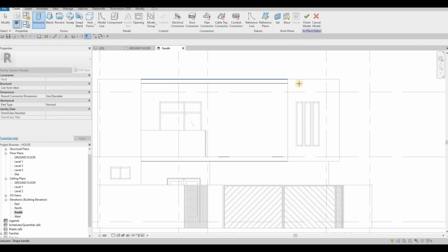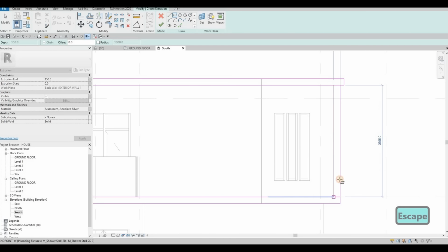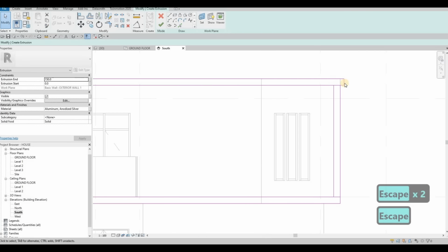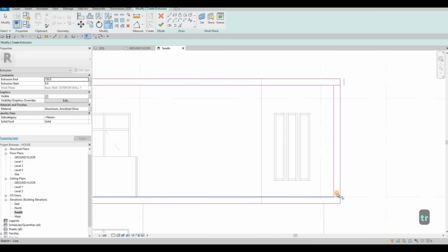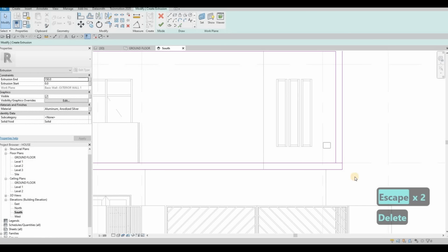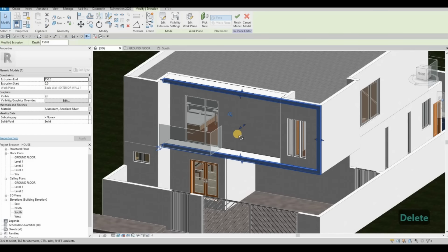Pick a plane, we're gonna select this plane now, and then now we're gonna tie everything all together by doing this, and then doing this right here. This one should be 200 as well. We could trim and extend all these ones right here, and then let's remove any unnecessary ones like that, and then click finish and go to 3D.